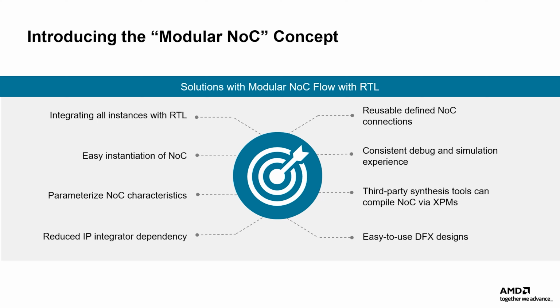Parameterizing NoC characteristics by using RTL, which enables scalability, flexibility, and reuse. Reducing IP integrator usage to its minimum essentials without losing any NoC capabilities in an RTL design environment, allowing users to still use the IP integrator for accessing hardened endpoints like the DDRMC, SIPs, or HBM blocks.